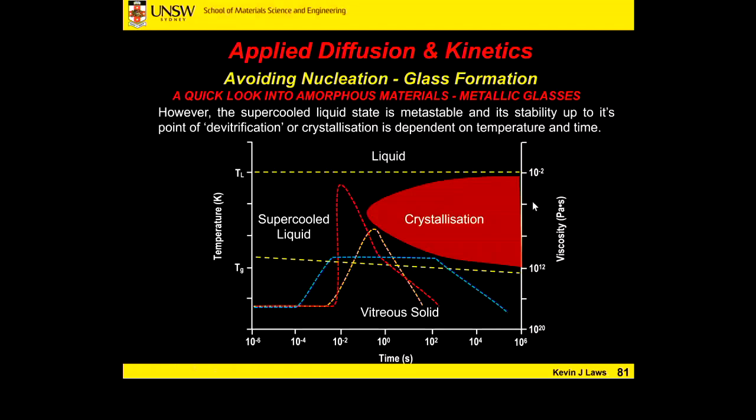Is it because you introduce cracks? No. This is nucleation and growth. It's dependent on temperature and time, how much undercooling we have. So remember delta T from Thursday's lecture. Here, in terms of time, we can have a large delta T before we crystallize. Here, delta T becomes smaller and smaller over time. So this represents the nucleation process and then crystal growth.